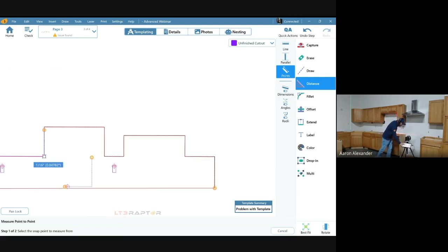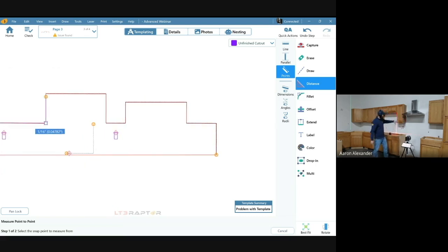Okay. Now with this situation, if we repositioned and I captured the rest of this from location number 2, right? What can go wrong there? We're within a 16th on our reposition, but what dimensions are actually going to be affected by this reposition, right? We're going to capture this edge here from position number 2, and we're going to connect, and we're possibly going to shoot that panel's edge from position number 2 and these things as well, right?